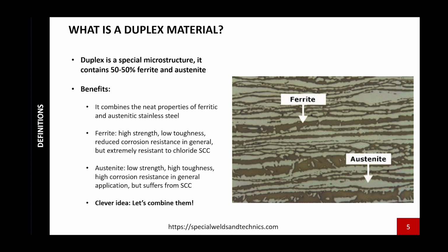Austenite has excellent corrosion resistance and high toughness. This high toughness makes them suitable for cryogenic application. Even liquid helium can be stored in a vessel made of austenitic steel.